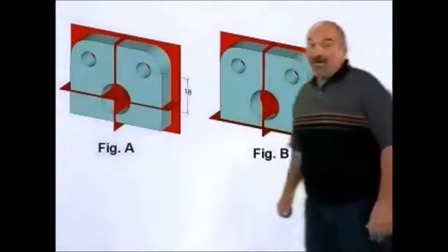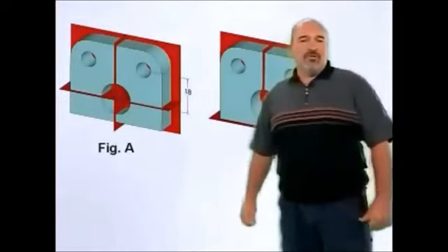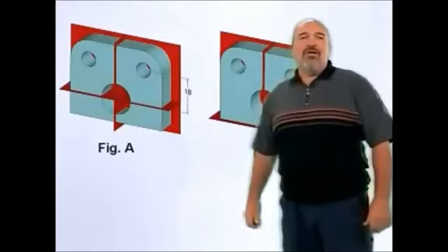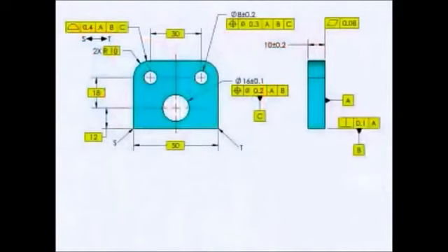The dimensioning may have thrown you off. You cannot go by the placement of dimensions like we used to in the old plus-minus days. You have to follow the datum precedence stated in the feature control frame. Because the large hole, datum feature C, is the 3rd datum referenced, it can only establish the measurement origin from left to right. The up-down origin is established by datum feature B, which is secondary.